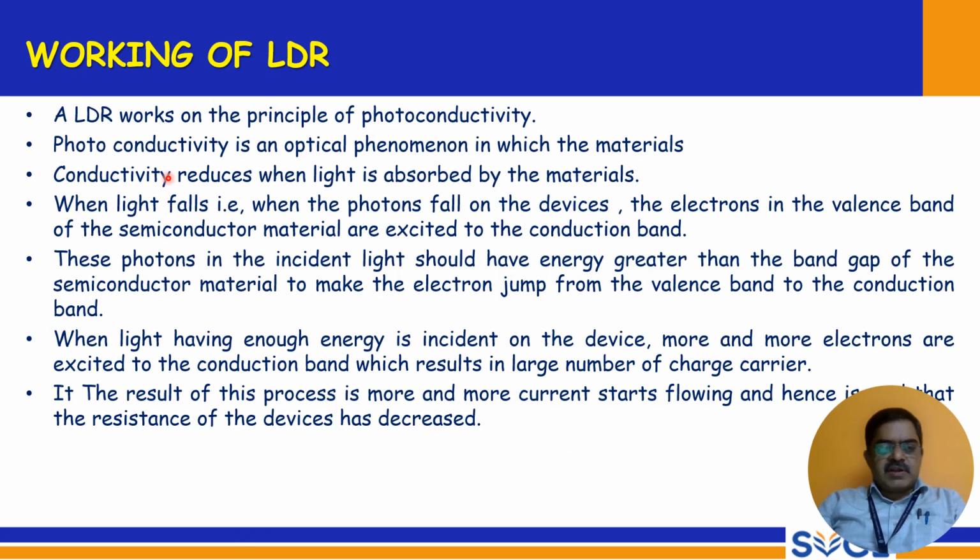Working of LDR: LDR works on the principle of photoconductivity. Photoconductivity is an optical phenomenon in which the material's conductivity increases when light is absorbed by the material. When light falls, that is, when the photons fall on the device, the electrons in the valence band of the semiconductor material are excited to the conduction band.